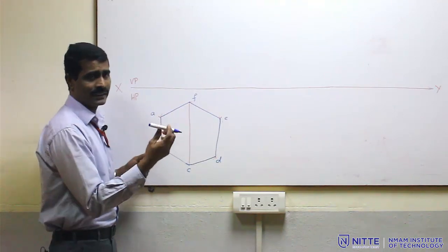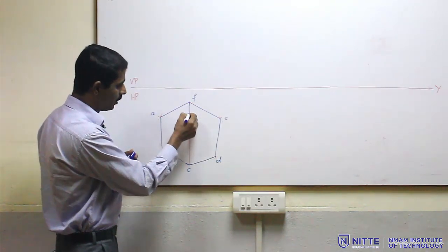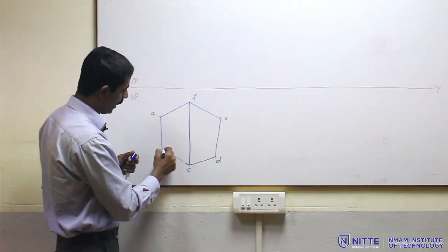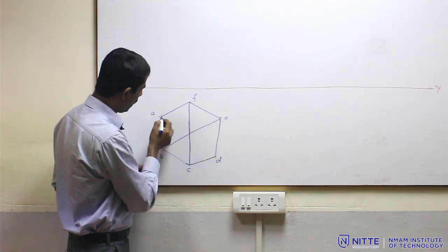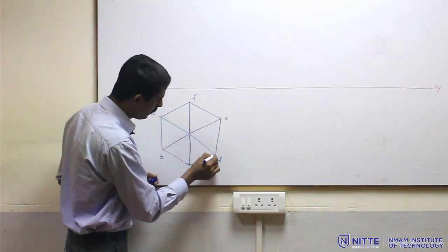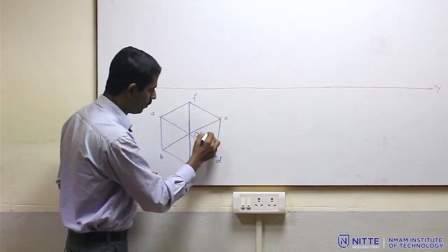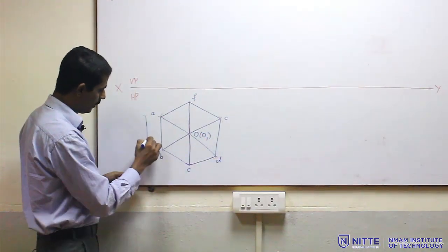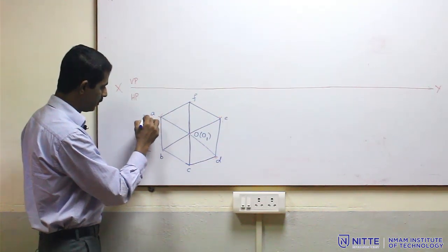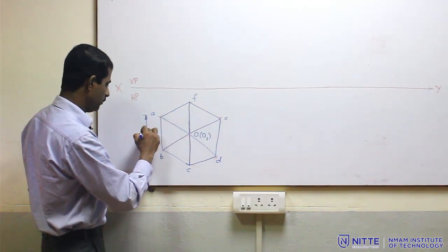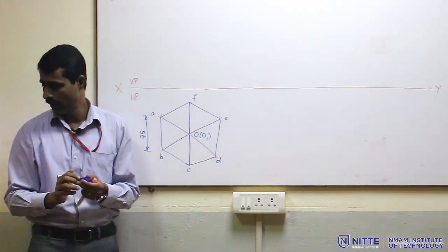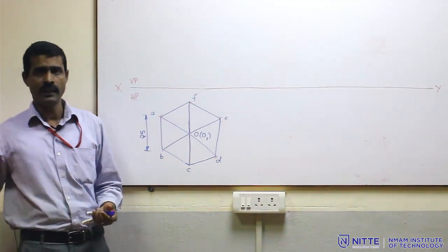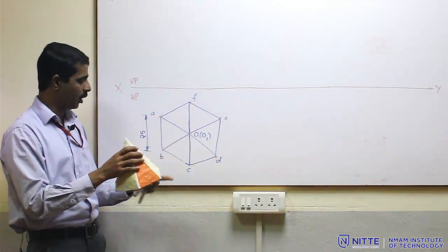And now to get the axis endpoints, as I mentioned in the beginning, draw diagonals, and these diagonals are dark as well, O bracket O1. So, this is the complete top view. This dimension I can write in aligned dimensioning method, 25 mm. Again, we can have a look at how the top view is obtained.